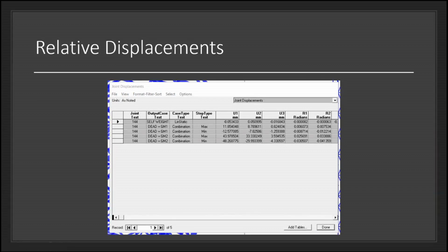So for the displacements as well as the accelerations, as I mentioned, these values in the table are for the single point at the top of the tower. Again, we want to note the X direction displacements. And here you can notice that the Y direction displacements are significant too. And this can be attributed to the torsional effects, especially for last year's tower because of the unique shape of the building.